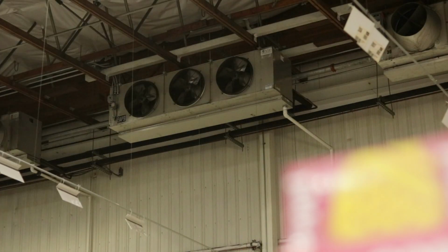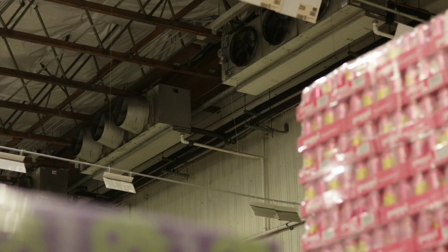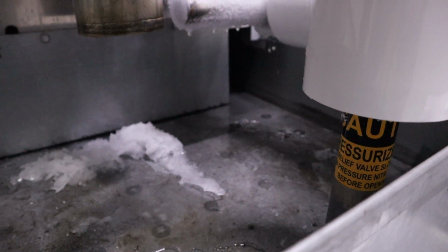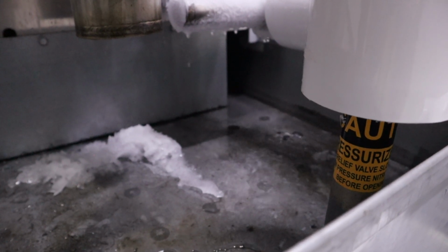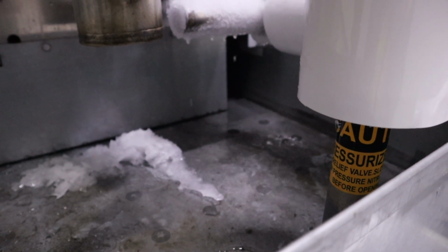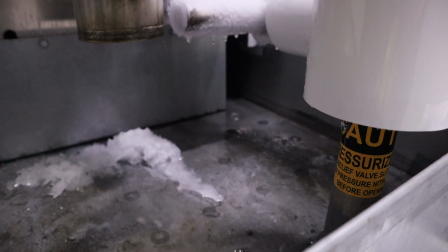To avoid the room temperature deviating too high during defrost, most systems are arranged so that the evaporators can be independently defrosted. Coils will alternate through a defrost to avoid significant changes in the room temperature. Air cooling evaporators will have a pan to collect water that drips from the surface during defrost. The drain pan is also susceptible to freezing, so it must be accounted for in the defrost system.